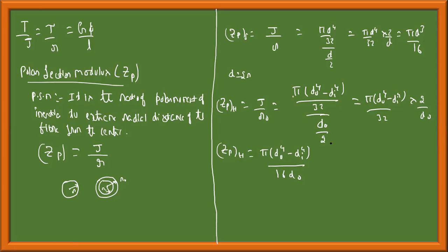Okay, this polar section modulus, why is it important? Higher the polar section modulus, lesser the twist, lesser the shear stress induced, and higher the torque withstanding capacity, which we will discuss. So this polar section modulus is very important.